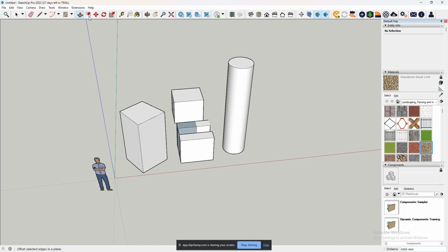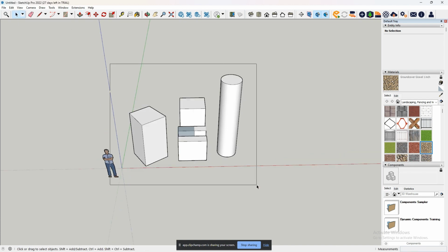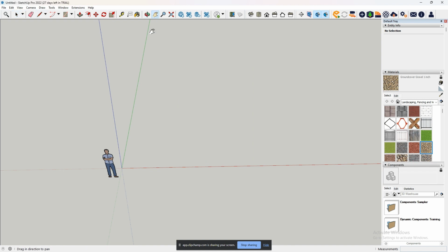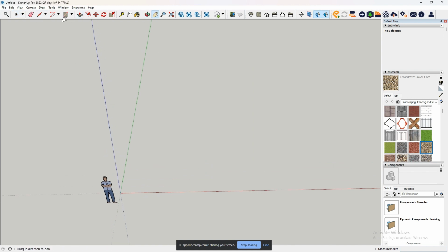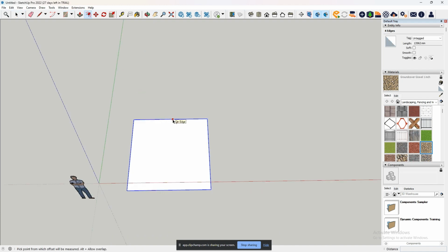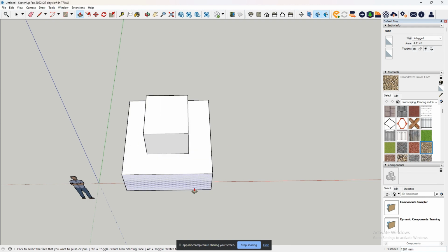And that brings us to next, the offset tool. So clear up the space one more time. The offset tool allows us to, as the name implies, offset different shapes. Hit the offset tool, and then you want to click on that where it says on edge, and that allows you, I'm not holding this down, I've just clicked it once, and now I can bring it either in or outwards to offset that object. So if I stop it right here, that is now an entirely new surface, as you can see right here. And now I can bring these up into different places, and you can do this almost indefinitely.